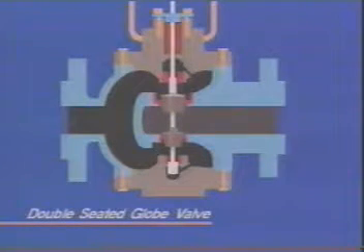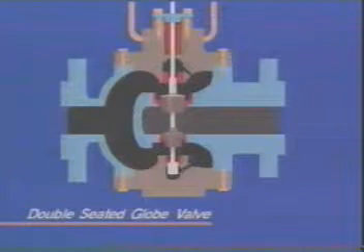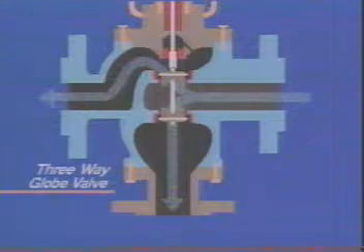You should also be aware that these valves may not seat as tightly as single-seated valves. As you can imagine, it's nearly impossible to close both ports simultaneously, especially when thermal expansion has affected the valve construction materials. Three-way valves are simply a design extension of double-seated globe valves.